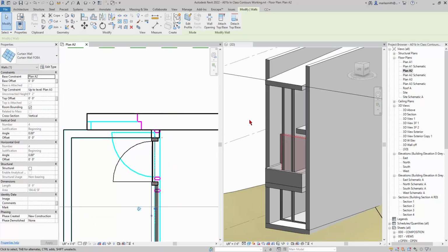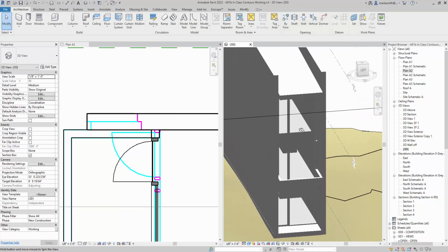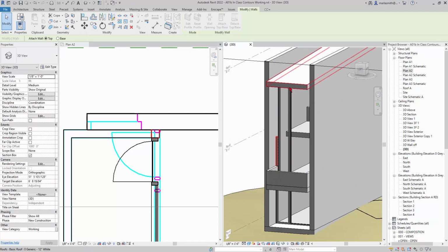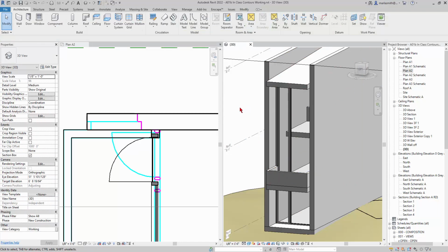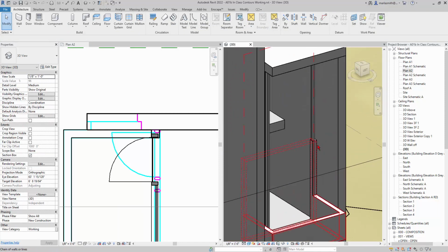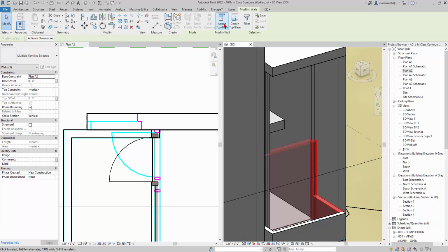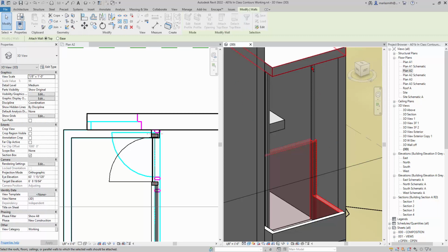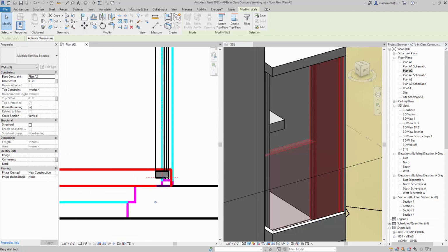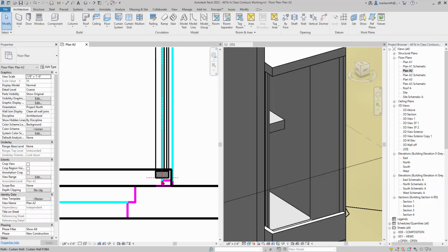So now if we look at our 3D, right, we've got 2 little walls and we need to attach to these guys. So I'll just do them one at a time. I'll just left click and attach top base, right, and then I'll spin around and pick this one, and let's attach base to there. And it looks like, see how they've sort of pulled themselves into the wall.